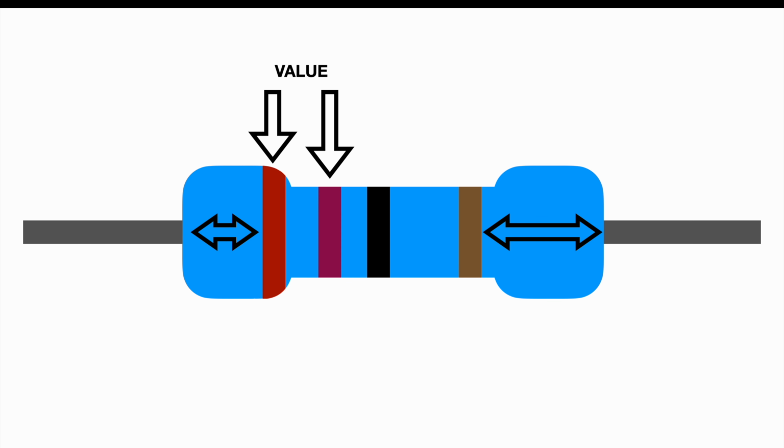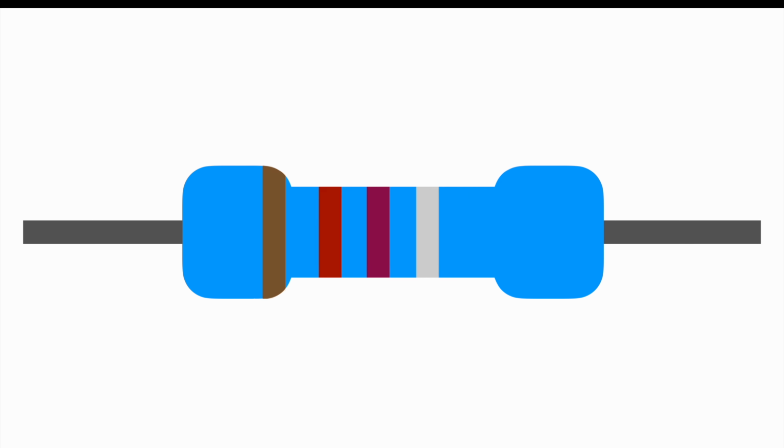But some of you may wonder already how to represent values of 1.27 ohm with only 2 digits. So that's absolutely true, and that's why we have to introduce another ring, a fifth ring. So by introducing this additional ring, we increase the digits we can represent on our resistor, and so the precision of a value we can represent. Of course, this needs to be represented in the manufacturing tolerance as well.